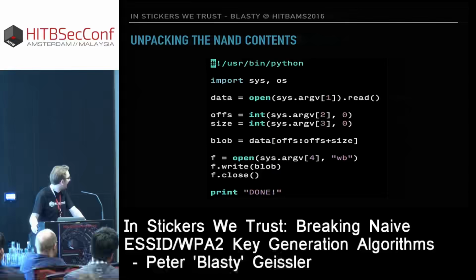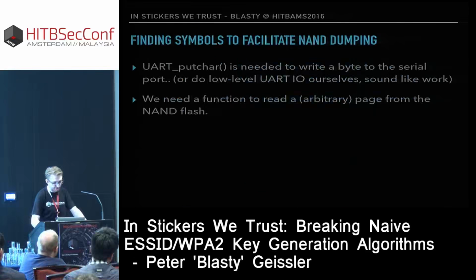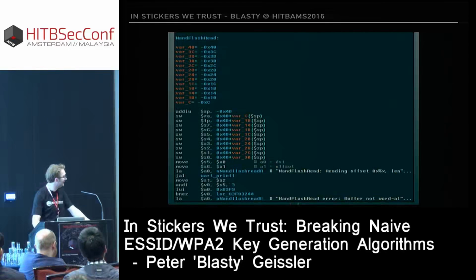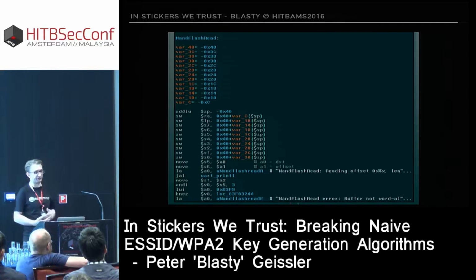So yeah, using this small piece of C code, I was able to dump out an end. It took a long while because this serial port is not super fast. So I just left it running overnight, and I made sure it spits out ASCII hex instead of binary. And the way I set it up is I just use screen as a terminal emulator. I see lots of people using minicom, picocom, whatever com. Don't use that, just use screen, right? Screen is an excellent terminal emulator. It can also do serial port just fine.